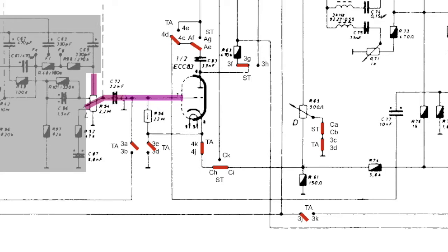It's going to raise it slightly because you've got cathode current flowing through here, it comes down to ground, it creates a voltage across here, so this voltage will not be zero, it'll be probably about 3.5, 4 volts, but it raises it slightly.